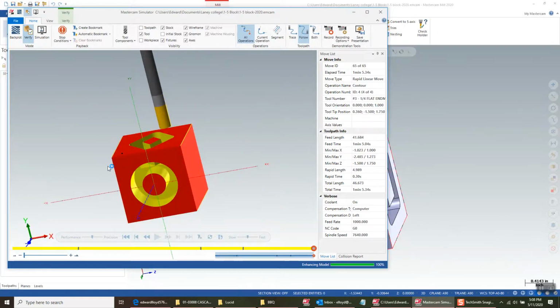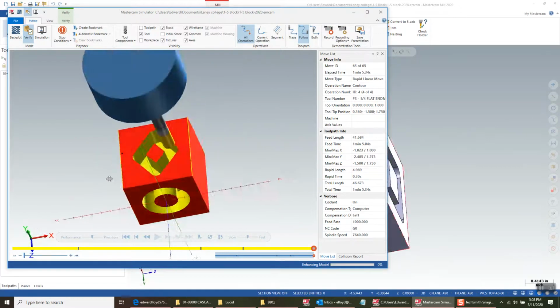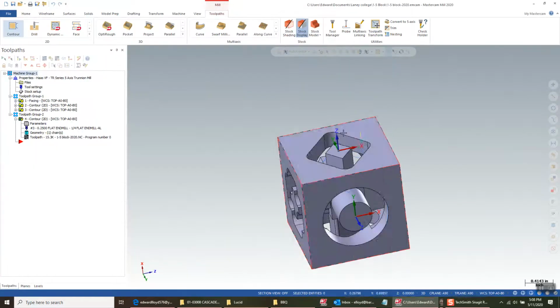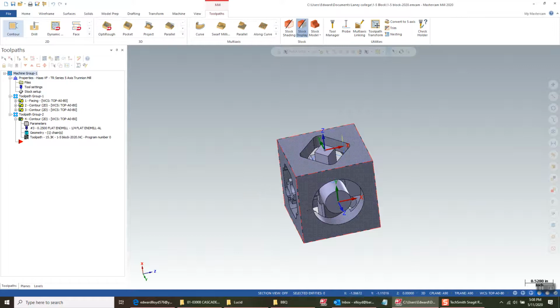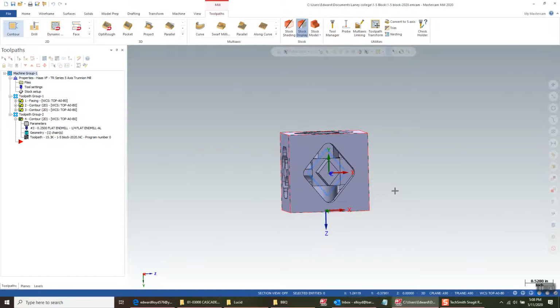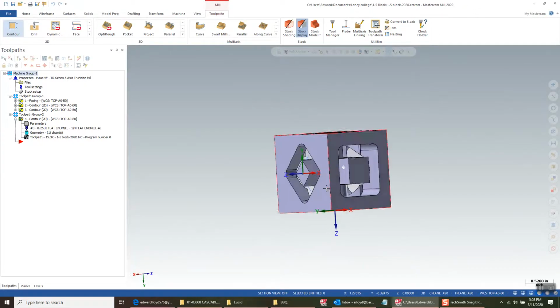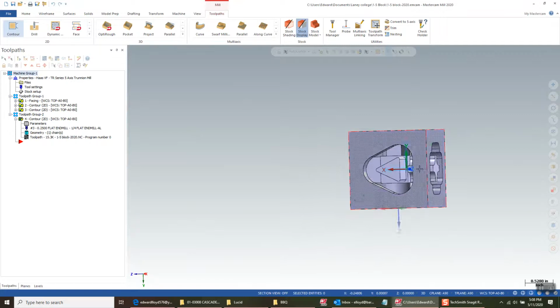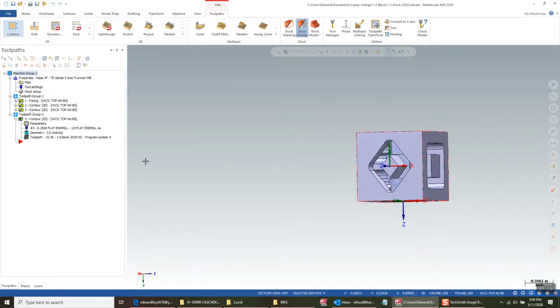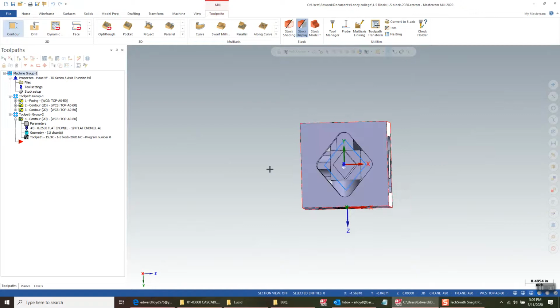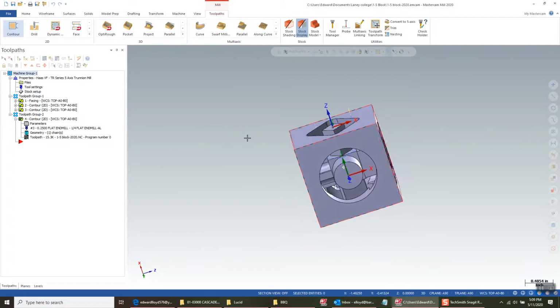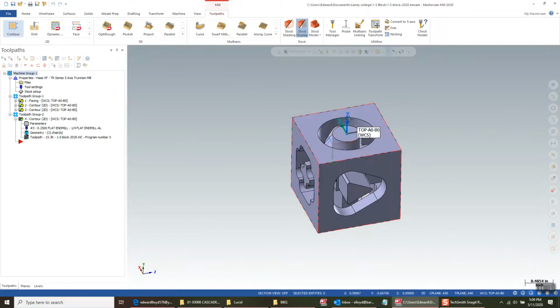Alright, so now we got two faces. And so we're going to continue like that with the other faces, but now we went from this face to this face by rotating about the x-axis. Alright, so now we're in this orientation, and now to get to the rest of them, we're going to start rotating this way around the part to get to the alternate faces. Okay, that's going to be B-axis rotation, because that's actually rotating about Z.